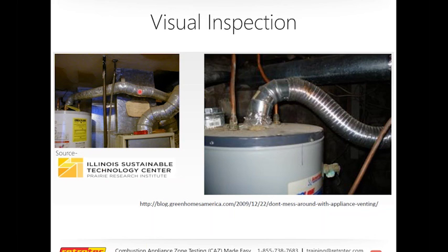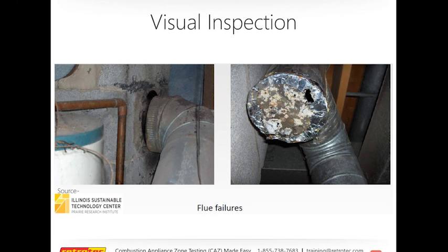Because if you can walk into a house and see that, say for instance, you're following an NFPA 54 code, or if you have specific standards about the pitch of a vent, say our state in Illinois used to have a specific protocol for the pitch of a vent, you want to make sure that it's pitched that way. And if it can't be pitched or if it can't be fixed, you might want to walk away, defer this job, or you might want to talk to the homeowner and say, hey, before I get started, I need you to fix these things because I cannot ensure your safety. And again, that's up to you.